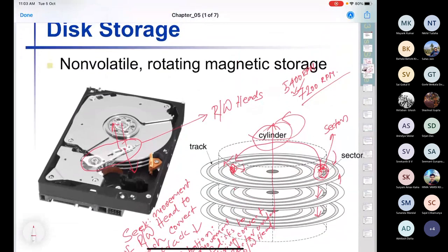There are motors, high-speed motors, etc. That's why it is quite difficult to decrease the voltage supply of a device which has a magnetic hard disk drive beyond a certain point, because the motor and this mechanical part need a minimum amount of voltage to rotate this at an extremely high speed of 7,200 RPM. 7,200 RPM is a humongously fast speed.